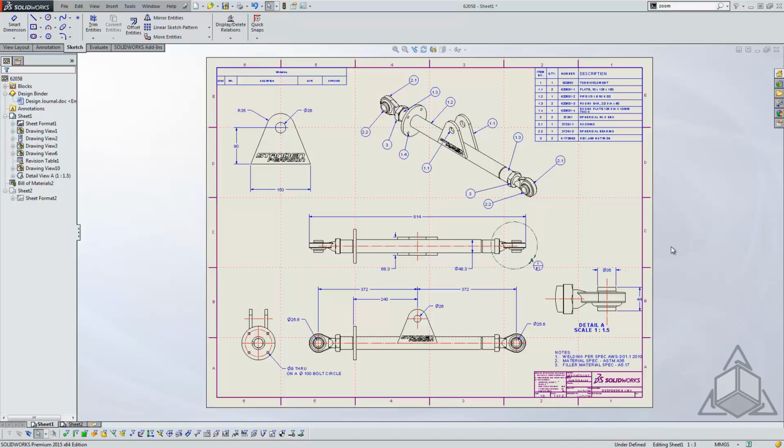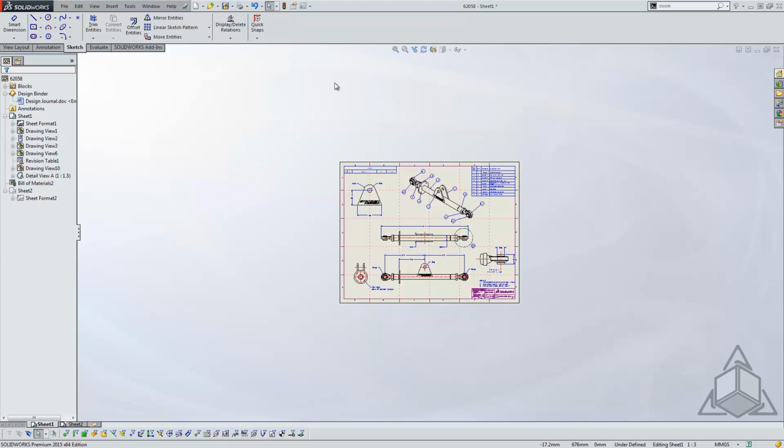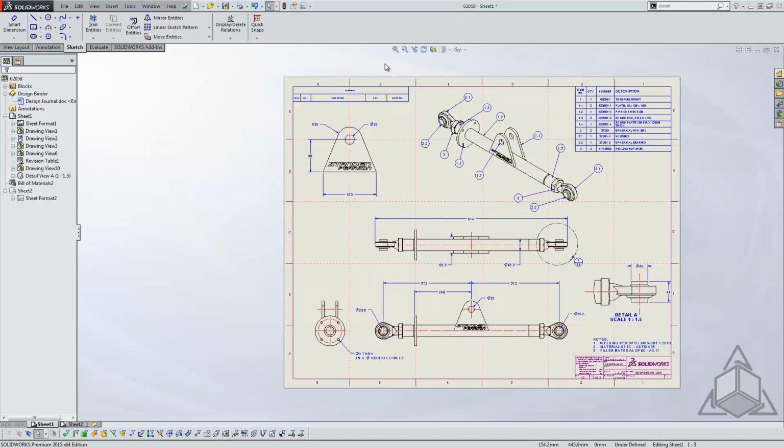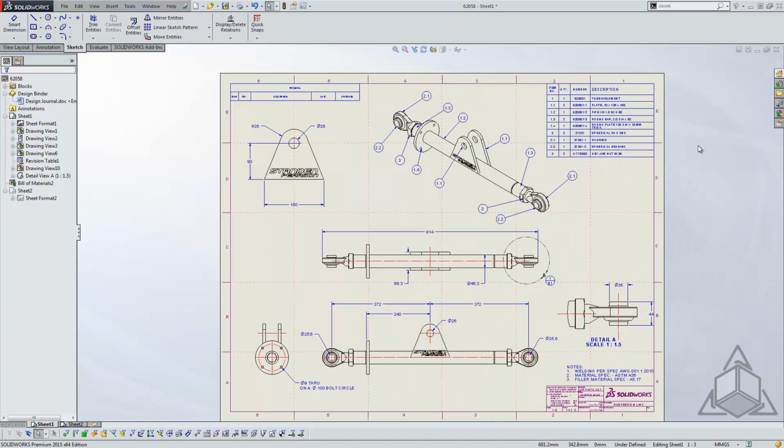This can be handy because a lot of times on drawings we've got things that we're just kind of storing off in space. Maybe we have a view that's just kind of over here that we're using as another reference for a detail view or something like that, or we have notes that have moved over, and every time we go to zoom to fit, it zooms to the entire region where we're working, where in reality we're just looking for the sheet itself. So zoom to sheet can be very helpful. I haven't set up a keyboard shortcut for that yet, but it's definitely a good one to customize. And of course you can always drop that in your heads-up display here through customize and get that on your sheet so that you can use that when the need arises.